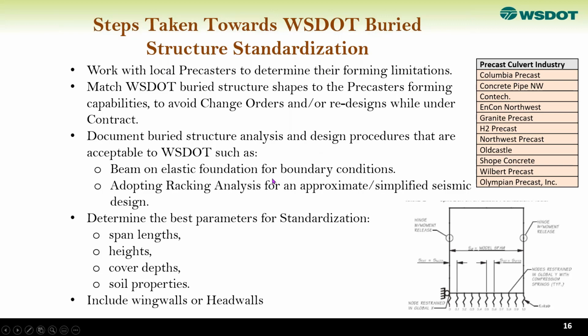We work with the local precaster to determine their forming limitations and match the buried structure shape that we are designing with their capability. In the initial phases, we had some designs that didn't exactly match what they do, so we did have some change orders or redesign. The standard drawing was to avoid that.